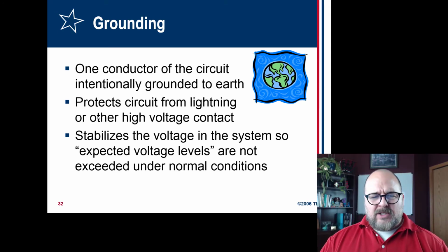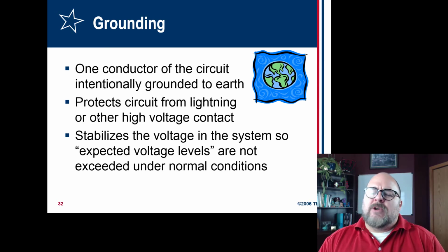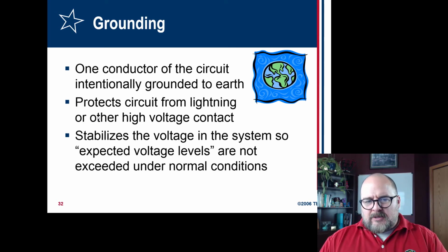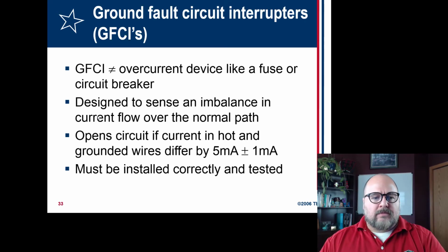It says protects circuit from lightning and other high voltage. I'm not sure if I fully agree with that. You can still damage equipment even though you have a functional ground, because again, electricity flows through all paths, not just the path of least resistance. It does stabilize the system though, provides protection.